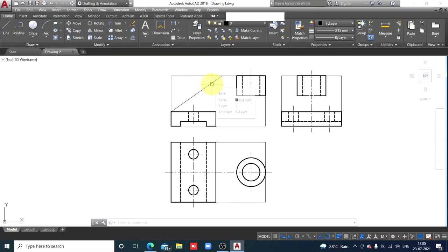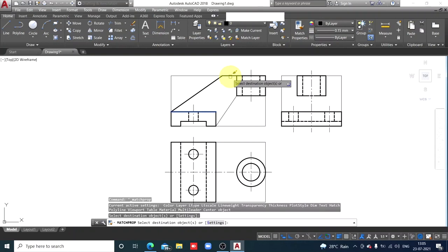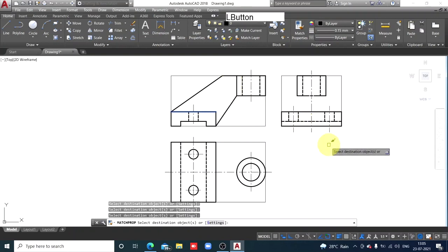And this is that non-principal edge I have completed. Also from this point to the curved surface of the cylinder, that is the boundary generator, I have drawn a line. Watch here, this is that line. Then again a line from here to the base corner. Match properties. So this is how I have completed the shape of the plate in the front view.